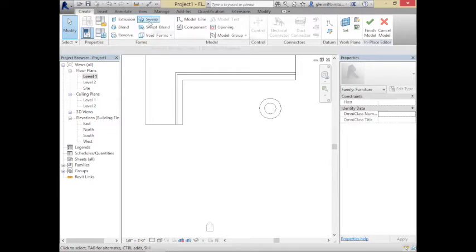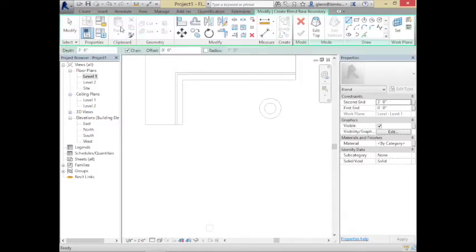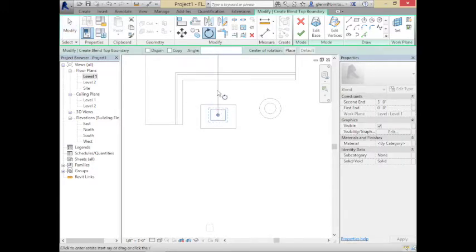Okay, so the same process again. You create a blend, right? And then you have the option. So we're starting with the bottom as last time. So Glenn, you say you want the square at the bottom? A square or a rectangle. Something where we'll see a nice twisty thing going on. Okay, let's do that. And then we click edit top to edit the top footprint. How about selecting all that and giving it a nice rotate? Do that 45.